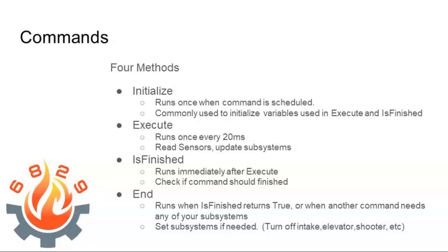If you say yes, I'm finished, by returning true, immediately it will call end on your command, right? There, you're basically going to do anything you need to do to wind things down. If you've reached your distance of 5 feet, you might want to stop. So end would say turn off the drivetrain.